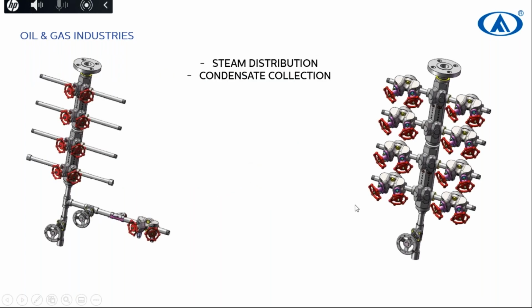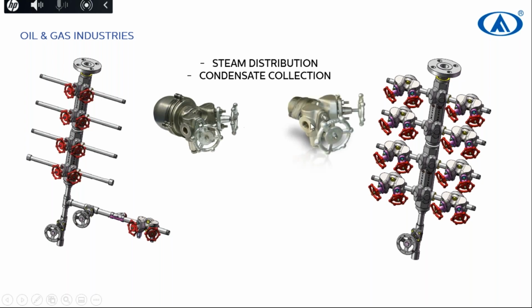So for the oil and gas industry, you can have 2 types of manifolds. One of them is for steam distribution, which is this one, and one of them is for condensate collection. And for this condensate collection, you can use these universal type steam traps with float type or with thermodynamic type, and also with thermostatic or bimetallic type. The body of the valves is the same, but the cover of the steam trap part is different.